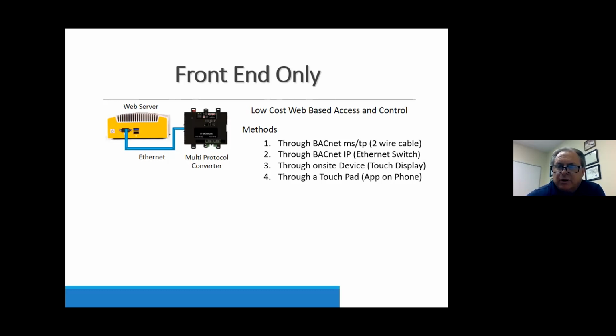So what are these controllers? What comes out of the factory already that allows us to see these things? So if we apply an integration application for a customer, what are we going to see? Well, some of the things that we can do. So for instance, let's go back to schools. If it's an area where the school doesn't have budget for a lot of DDC to take over a lot of applications in the facility, they're okay with programmable thermostats, they're doing the things that they need to do to be energy efficient, that type of thing. Still have to have outside air, still have to bring in ventilation for the facility. It needs to be controlled airflow.